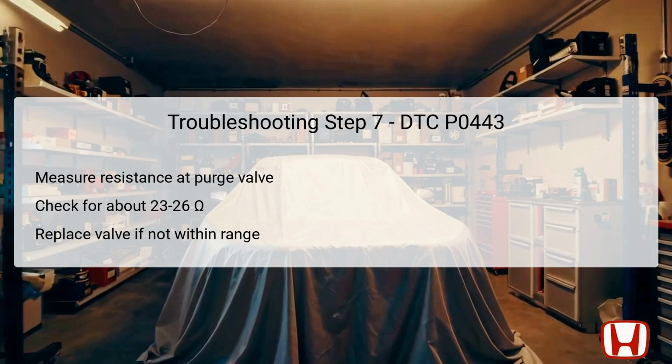If the resistance is within the range, you can update the PCM if it lacks the latest software, ensuring optimal performance. However, if the measurement falls outside this range, it indicates the valve has failed and should be replaced, followed by a verification of the repairs done.